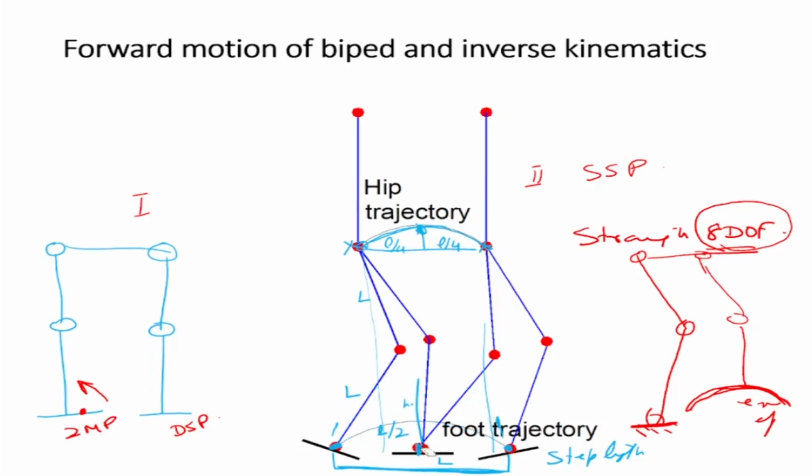So what we do is when we're trying to optimize, I'm saying that the hip trajectory is constant. I'm giving it a particular height, and I'm making this constant. On the leg trajectory, we'll find 2 points like this on the trajectory, and then fit a spline, and then find the energy that is consumed for walking on the spline. So the hip trajectory, I'm keeping it fixed, so it will have a trajectory like this. So I'll keep that height fixed. Then I'm going to find 2 points. That means 2 heights actually.